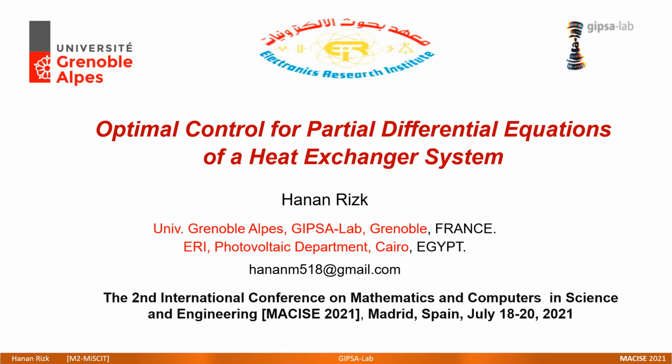The high effectiveness of the counterflow heat exchanger makes it one of the most popular types of this heat exchanger system device. Besides that, the double pipe heat exchanger, which is very suited for high pressure and temperature applications and low flow rates, can be used in applications of a small heat transfer surface because of its small amount of heat transfer per section.